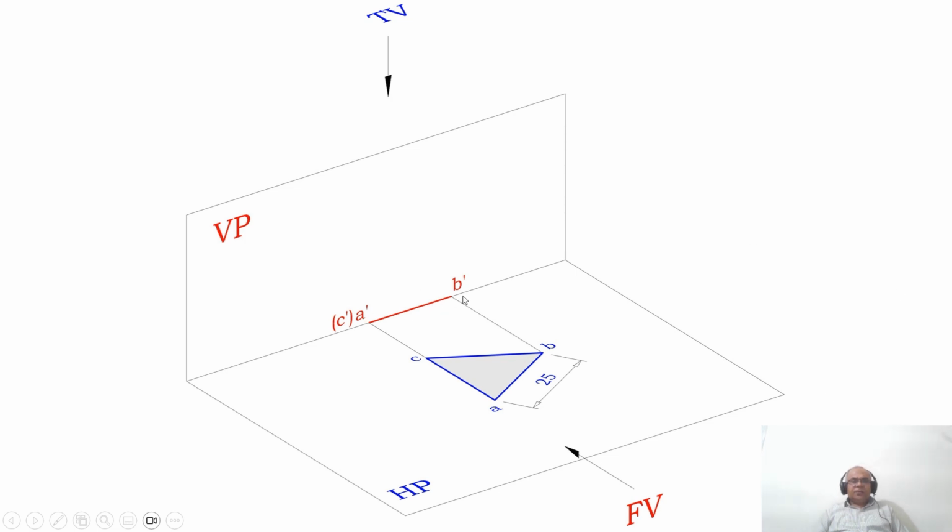And then whether it is resting on the edge or the corner, always the initial position has to start from the top, because once the surface is parallel to HP, I can keep the lamina on HP, because it is resting on one of its corners on HP.